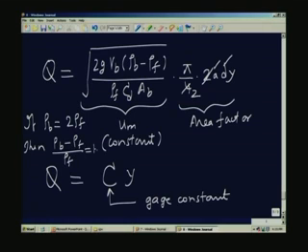So, the density of the bulb and the density of the fluid both drop off, and it becomes a very simple expression. So, this will be 1. So, it will be 2 g V b by C d A b under square root of, that will be the value of C. Okay. This is a specific case where the density is taken equal to twice the density of the fluid, then the density term drops off from the equation.